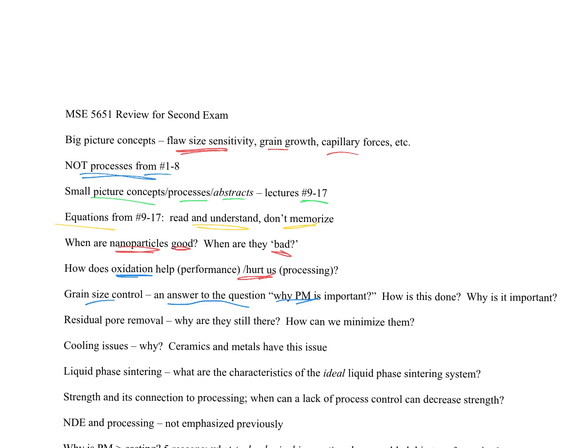And so this is a significant benefit to us, especially when we're talking about these biomedical alloys where you're trying to squeeze every last piece of performance out of these things you possibly can, and so you want to make the grain sizes as tiny as possible. So when you cast a large piece of metal, that is oftentimes not possible because that metal can stay hot for a while. And so we should know how we control these grain sizes and why it's important.